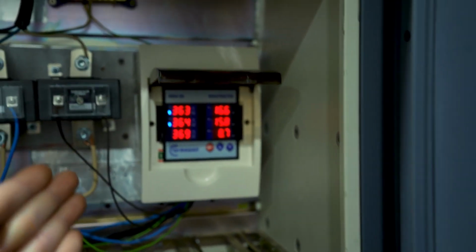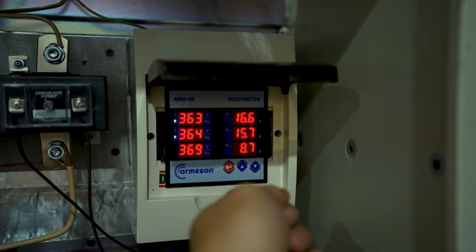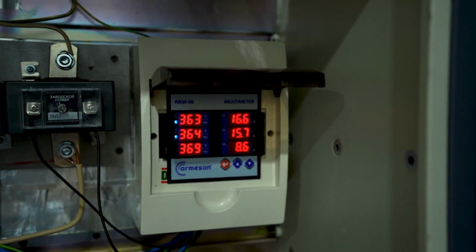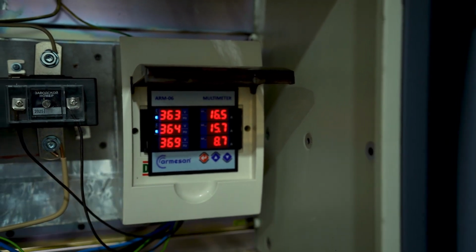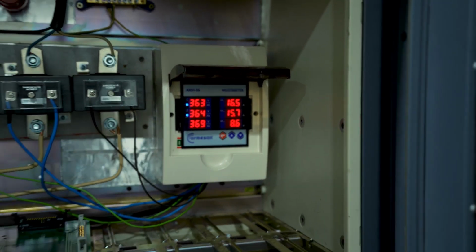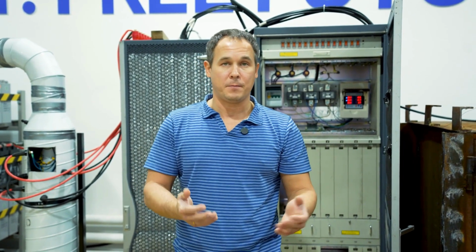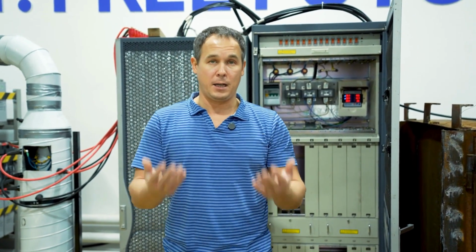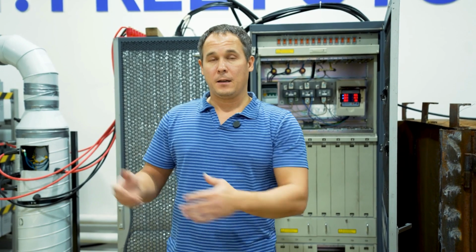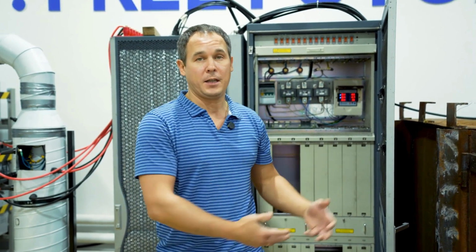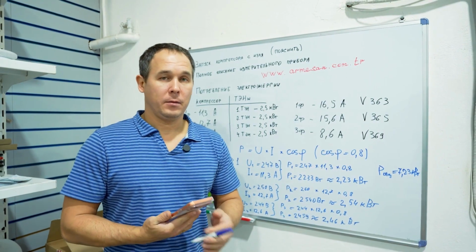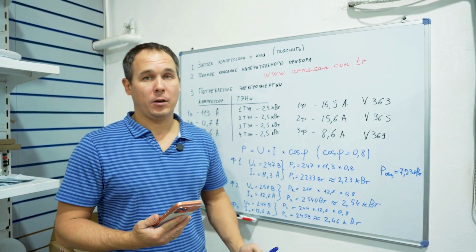The power consumption. Please record the power consumption by the external consumer. These are amperes again. We can see the volts and amperes here. And now we can calculate the total kilowatts using the mathematical formula. I'll write it on the board now, and I'll write down all these individual readings on the board. And we'll calculate together how many kilowatts are consumed by the compressor and how many kilowatts the external consumer uses. I'll write down the readings now. Dear colleagues, here we present the calculation for your attention.